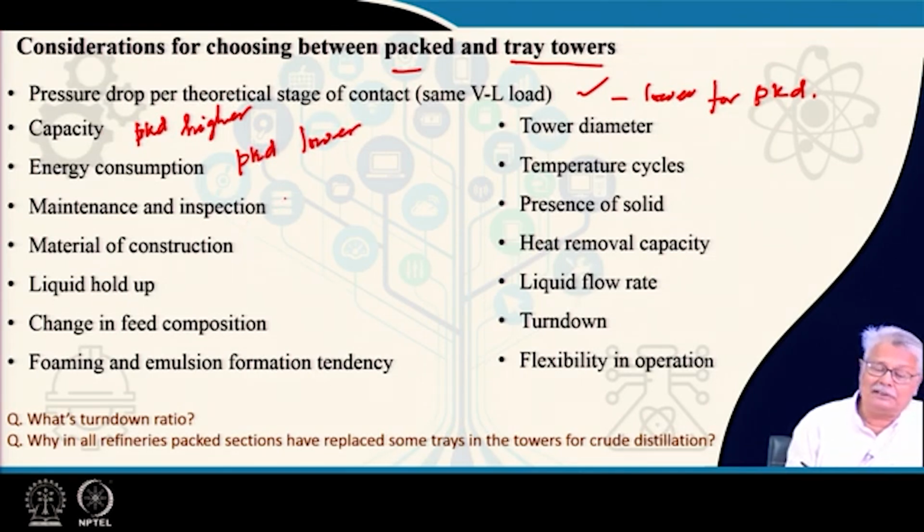It is more difficult to talk about the maintenance and inspection facilities. Maintenance required for the tray towers and packed towers depends a lot on the type of service that it is providing. For example, tray towers, the trays have a tendency to fall in case of pressure surges.